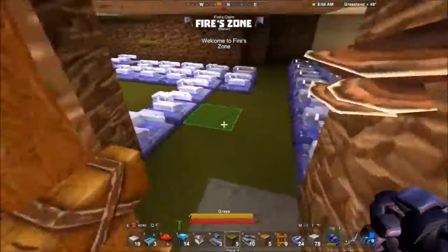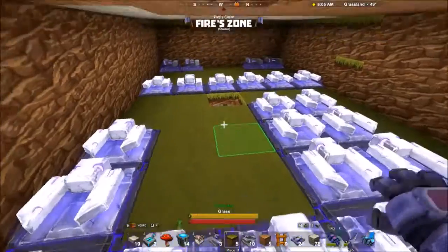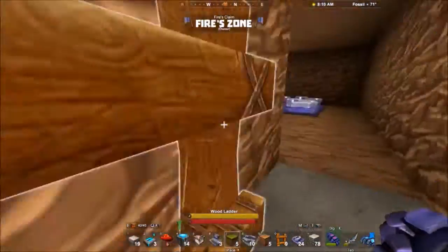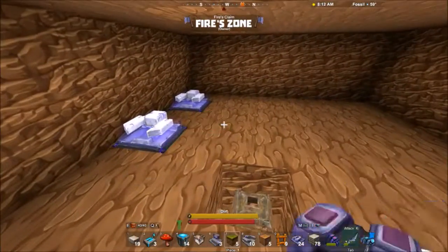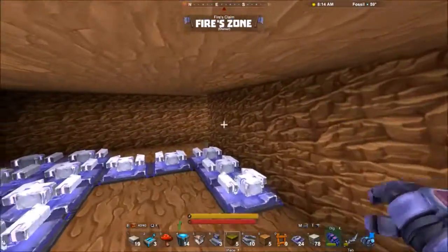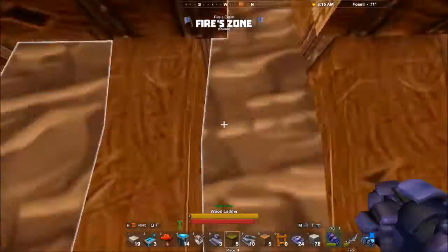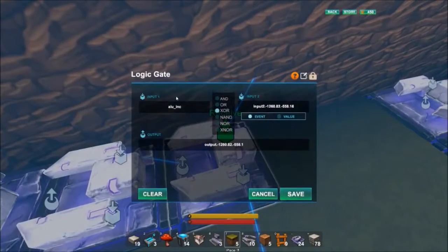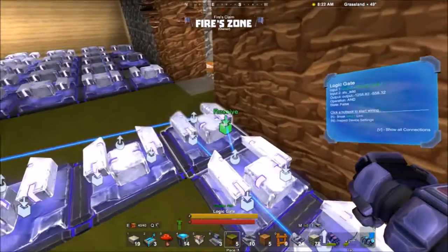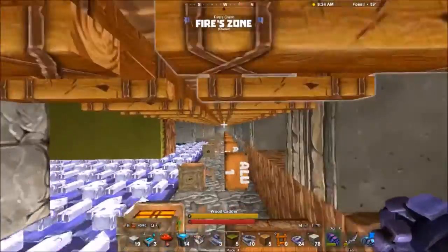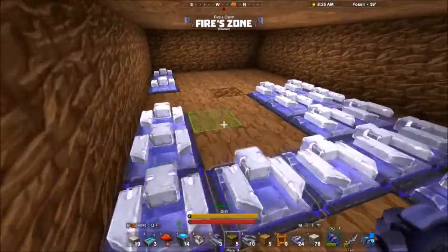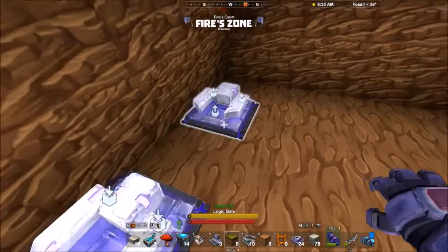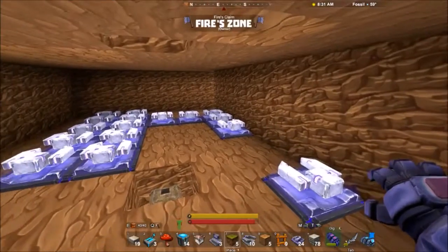So yeah, that's how these two signals are generated, and they are needed for the look ahead carry logic. We're here on bit 1. The only way you get a carry on bit 0 is through the increment, which is the switch that we have on top. That's the only way you can get a carry at bit 0, because there's no addition that has happened beforehand. But on bit 1, there's one addition that happened beforehand. So you actually have two ways of getting a carry here on bit 1.